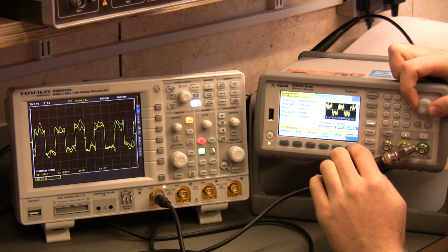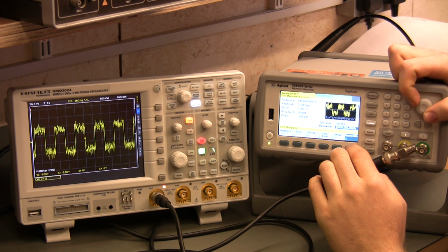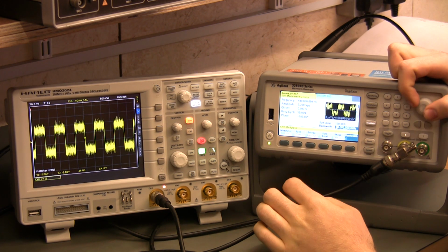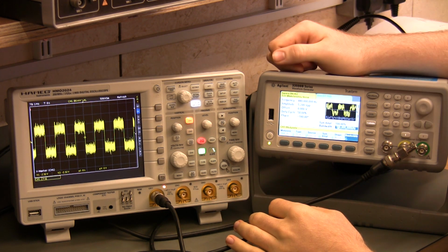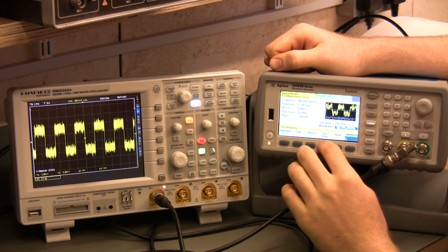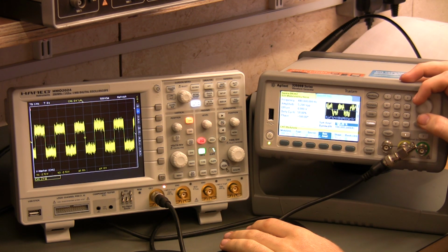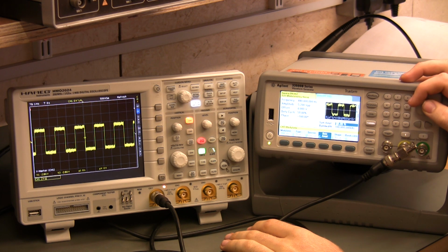Now we've got two controls. We can control the bandwidth of the noise. See up here we got up to 10, so let's take up to a much higher frequency there. So 100 kHz noise. We can also, so this is 100% modulation on this, we can actually dial this back.